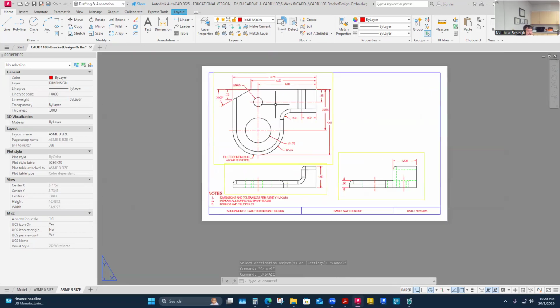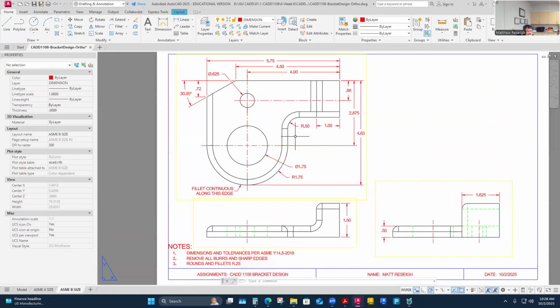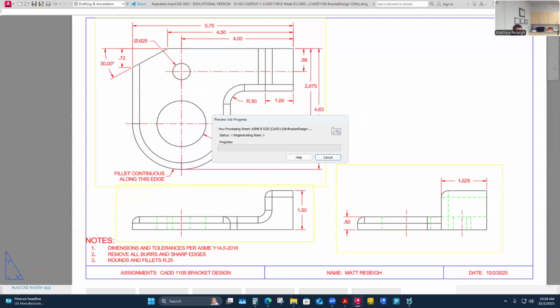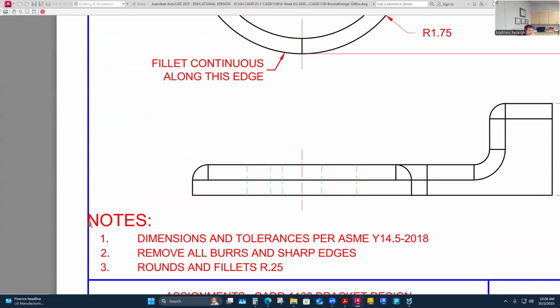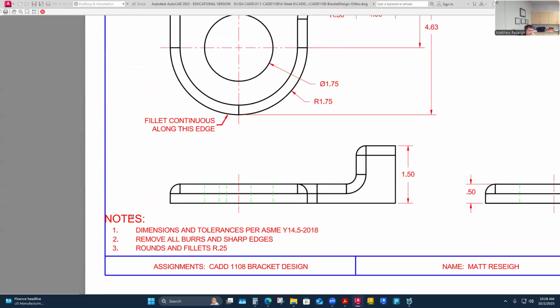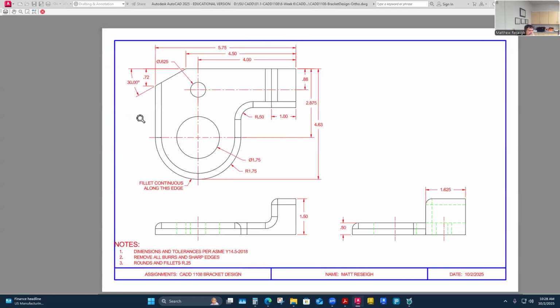And then my hidden lines, they seem to always be a good line type scale on these inch drawings. So I think I'm happy. Let's Control P this thing, see what the PDF looks like. Looks pretty all right. The N on my notes is clashing with my border. I need to move that in just a little bit. So be real critical when you come to this point. This is what you're delivering to someone. So this is technically probably the most important point to make sure everything's clear, legible. This is going to become a PDF or even a printed sheet if I need to.